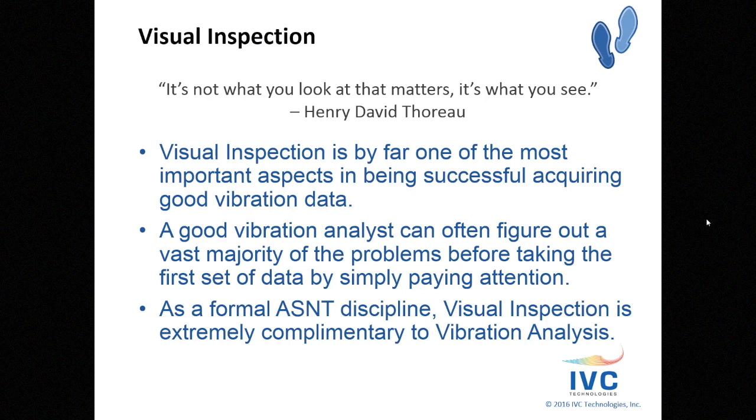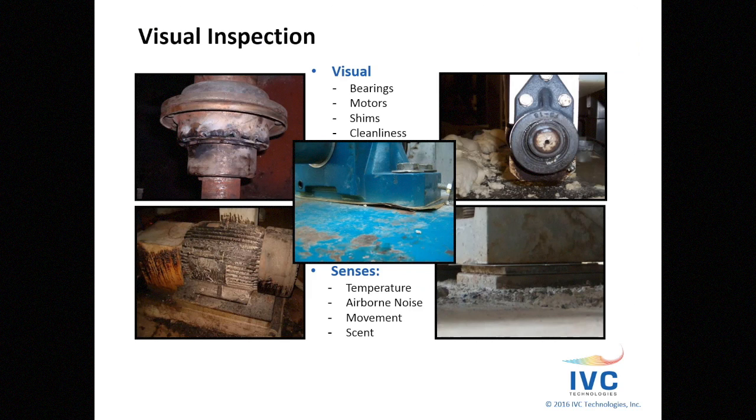You shouldn't go out there in the field and just blindly take data. Pay attention to the machinery that you're around. Visual inspection. Here's some examples of things that you're supposed to be looking for. What's the condition of the bearings? Look at the motors. Look at the shims. The general cleanliness.